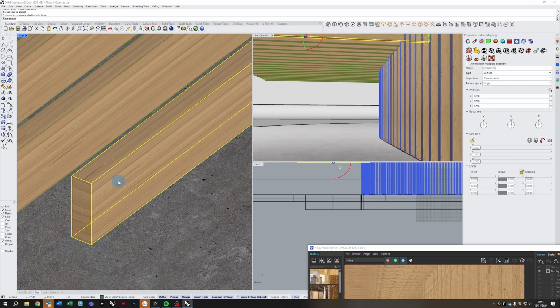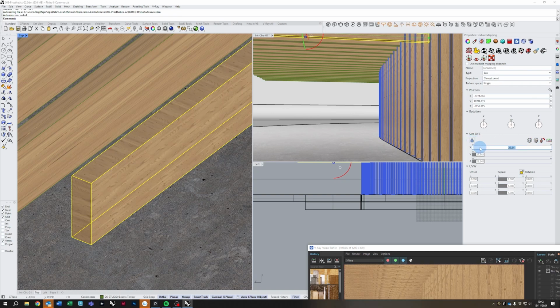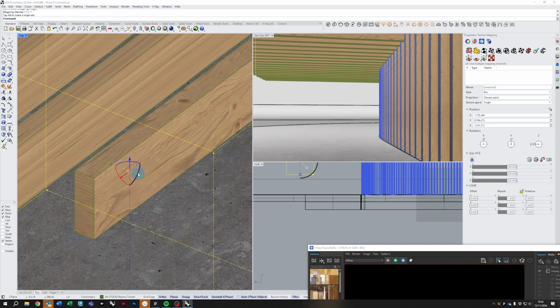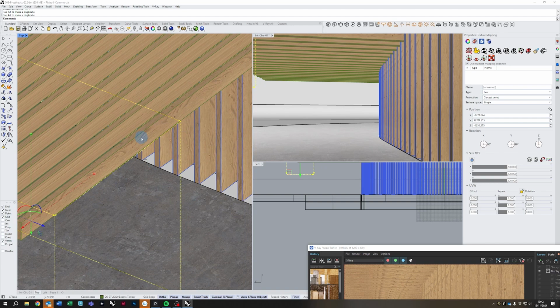And then you have to go in and do the same for this one. I will just explain how this box mapping would work. If I didn't just confirm the bounding box, you can basically draw what this box would look like, and you say OK to capped, and now it's applied it to here. My scale is off, of course. Tell this to be 200 again. This is wrong, so I will rotate it like this and rotate this one like that, and we're done.